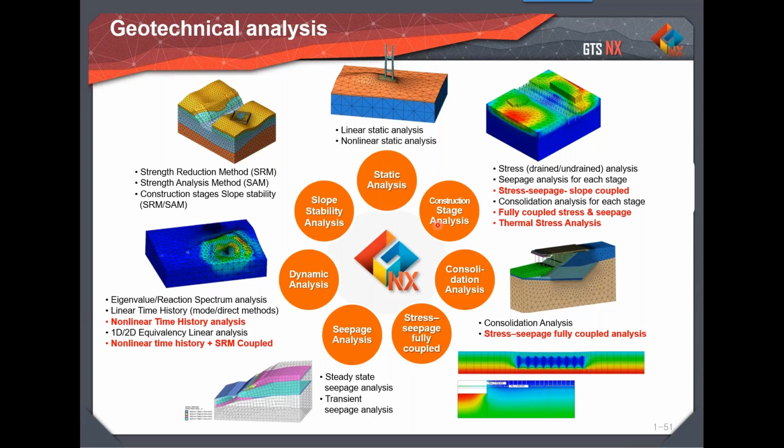So as you know, soil is a highly nonlinear material. With the change in the stress, its behavior changes. It may move from elastic to plastic very easily. Such kind of things generally we can consider when we do it in the construction stages. Of course, we can do it in the static direct analysis as well, but we need to provide some increments. But here you can actually provide the excavations in increments as well, and deactivation and activation of your struts in different stages. So basically, the phase analysis which you do in, let's say, PLAXIS.